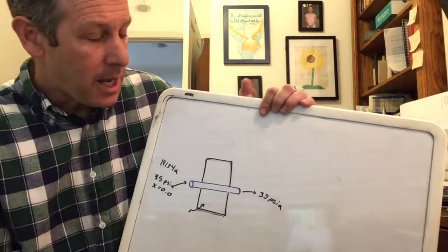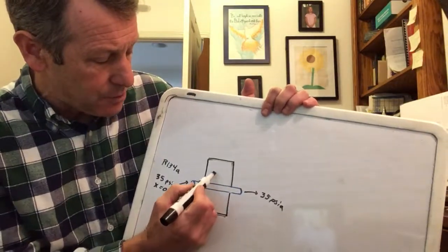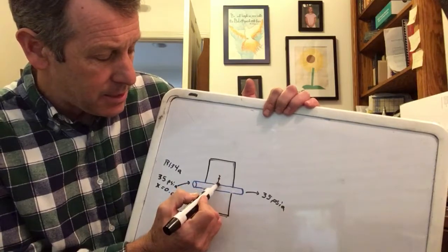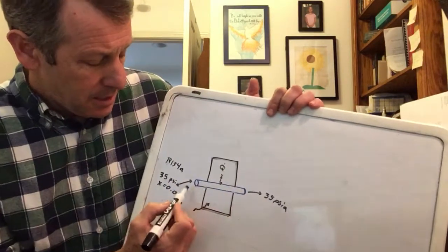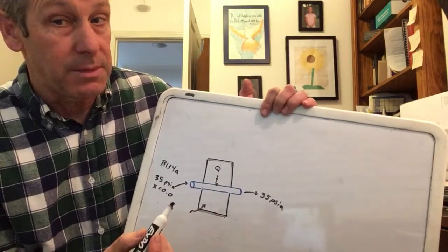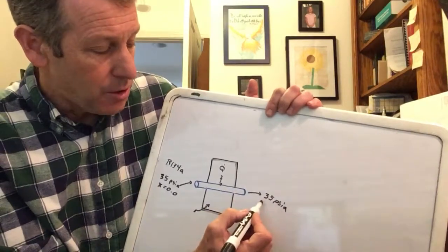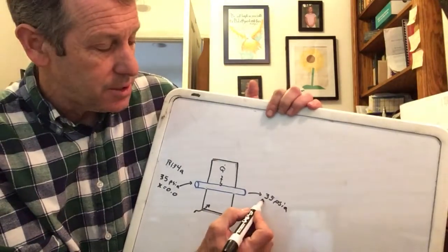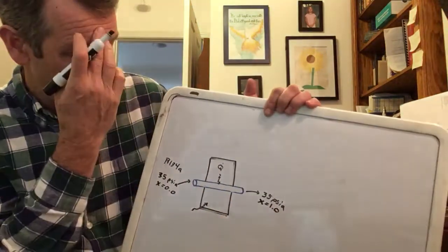And I'm going to go ahead and give the typical outlet conditions. What happens is, as the refrigerant goes through there, heat goes into the refrigerant. If it is a saturated liquid and you add heat, well, saturated means about to boil, so it essentially evaporates as it goes through and picks up heat. So many times these systems are adjusted so the refrigerant comes out as a saturated vapor, x equals 1.0.